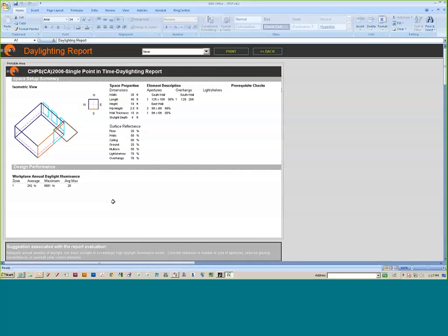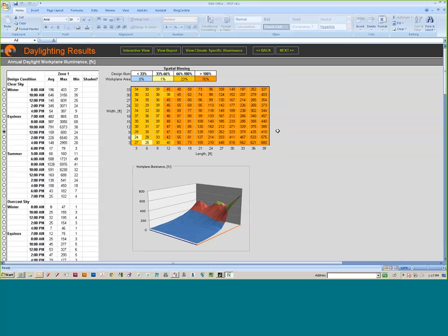Okay. So one way to check that is if you hit back on the top right-hand corner. See at the very end of your east wall by that 39 length, you see 680 foot candles, 575, 410, and so on, right? So your normal design illuminance that you're required to have in that space is 40-foot candles. We get glare if the amount of light is 10 times above your design illuminance. So if we're required to have 40-foot candles and you have 400 plus, then that's the potential to cause glare, and that's what this program is telling you right now.